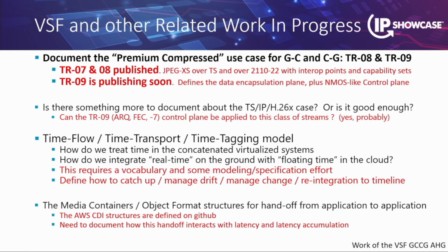The VSF has recently published TR08 and TR07, and TR09 is underway, which describe very exactly how do you use JPEG XS to do this? How do you map it into the 2110 timing model? How do you map it into really all the way down to the network packets is described by these documents. And that's great, right? Because it's a well-described, fully articulated system. And it's built on top of SMPTE 2110. It's built on top of the ITU JPEG XS codec. So literally every bit of the signal down to the wire is defined well.